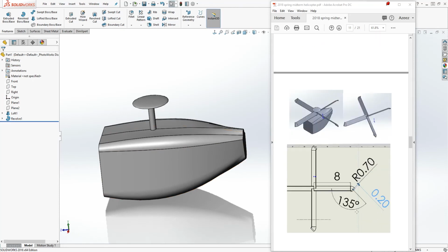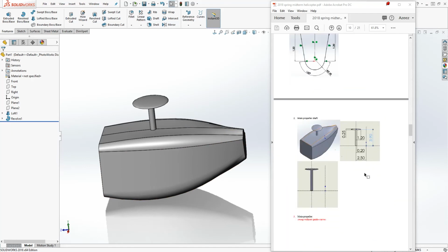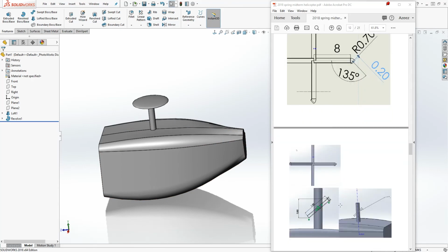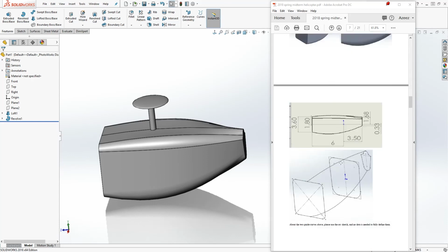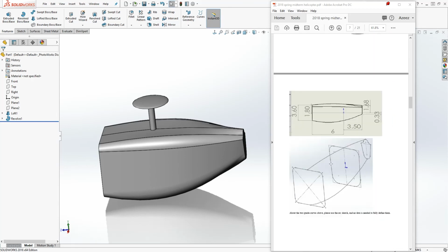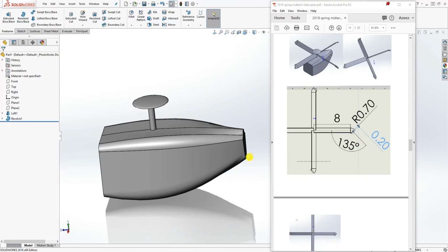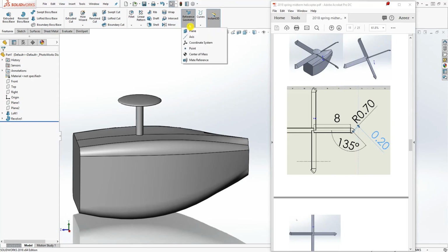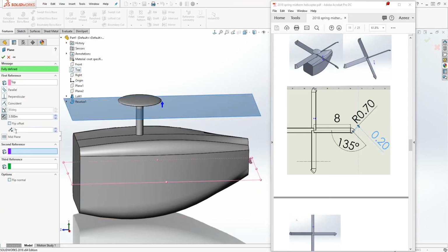So the next part is we need to draw the main propeller. So we have the sketch and the profile over here, and we just need to figure out the distance. So going back to this again, the propeller is 3 from the center line. So let's come to this sketch. So this one we are going to use the sweep tool. Come to your reference geometry plane, and on this drop down, we're going to select the top plane and offset it up 3,